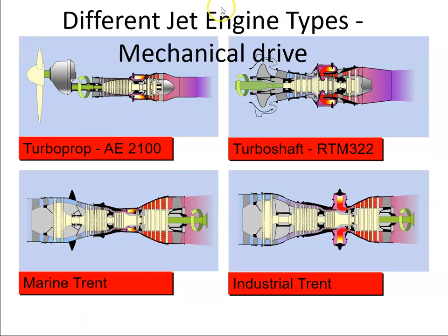Another type of engine then is the turbo shaft. So again, there's a compressor, there's combustion, there's turbines, and the turbines go onto a gearbox, and this shaft then will drive. So for an aircraft, it might drive a generator. Okay, so we might have a generator here that generates electricity for the aircraft, and that will be like an APU, auxiliary power unit, that's in the back of an aircraft. Or it might go on to the gearbox of a helicopter, for example.